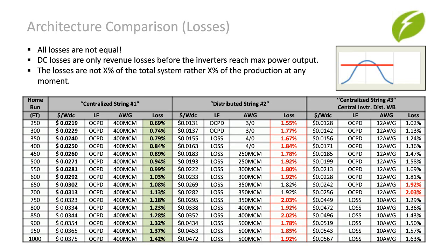Looking at the power curve at the top right, we remember that the higher the ratio, the wider that curve is. We reach the point where the inverters start clipping power earlier and stay there later when more PV power is delivered to the inverter. A 1.5% DC loss will slightly narrow the curve, but not be a 1.5% loss in total power because we haven't even reached that peak yet. Once we do reach the peak, or clipping red line, that DC loss is immaterial because the inverter can't process all the energy it receives anyway.